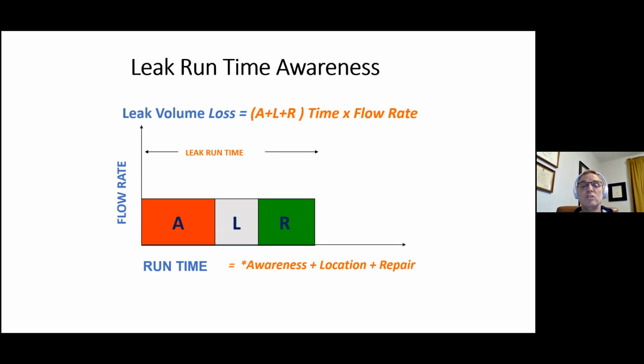But each one of those takes a certain amount of time. Sometimes awareness could take weeks, could take months. Location could take even a week sometimes, and sometimes it might even take you a week to get a crew out to repair it once you know where the leak is. But in best practice, certainly, you want to minimize all of those three blocks of time because money is being wasted during that time frame.